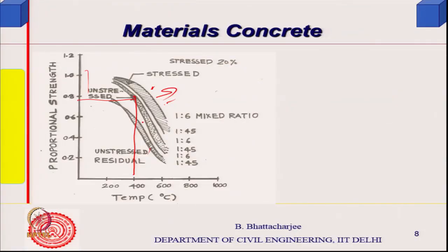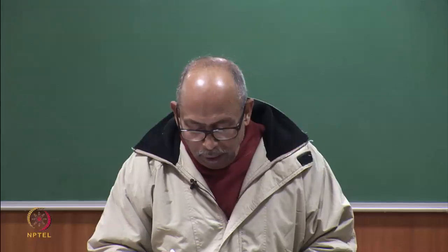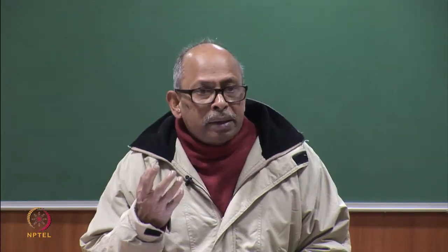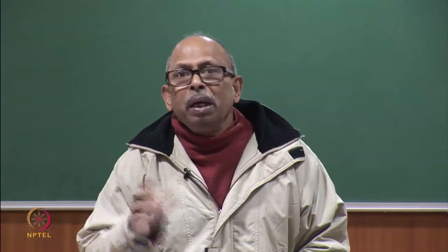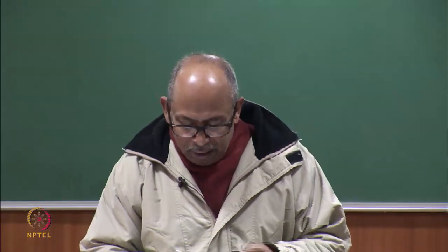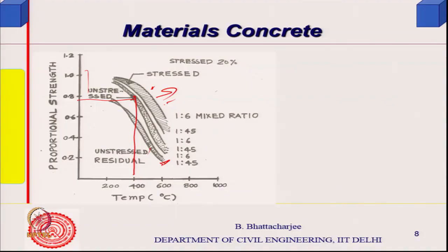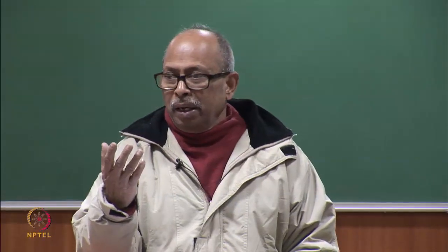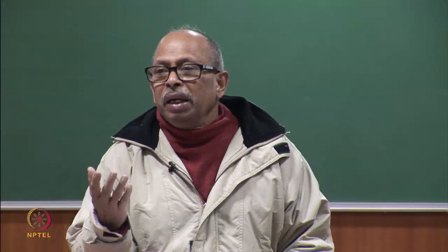So, here essentially that is why it shows you higher. When you do not stress it shows a little bit lower, and unstressed residual means you have heated it up, a lot of degeneration has already occurred, then you have tested it, obviously you get it least. And what is its implication? Implication is post fire load carrying capacity of the structure.